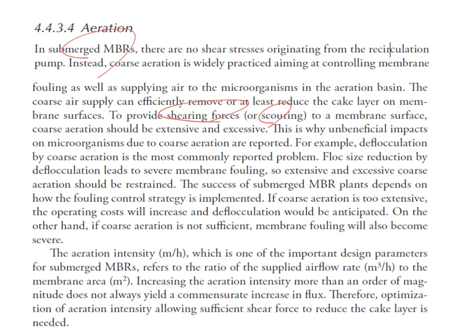So it's like we have some brushes and we scrape the membrane surface, and in submerged membrane systems this brush is the bubbles generated by this aeration, and it just scrapes or sweeps the surface of membranes so that this foulant can be detached. The success of submerged MBR plants depends on how the fouling control strategy is implemented, especially using coarse aeration.